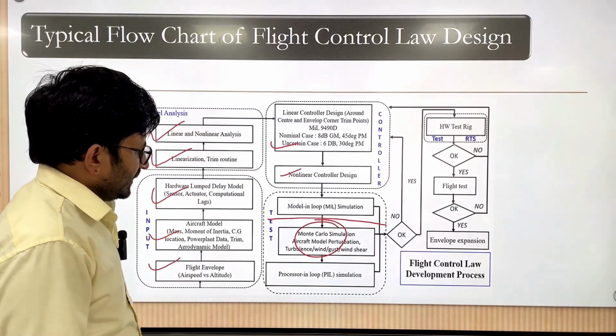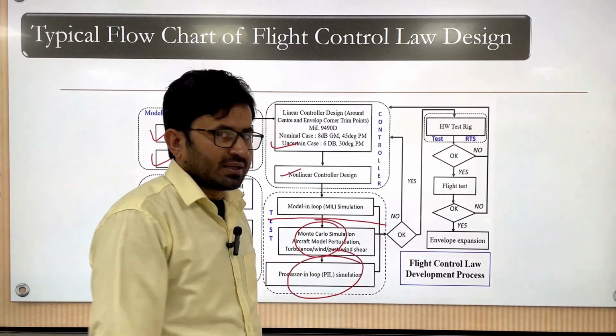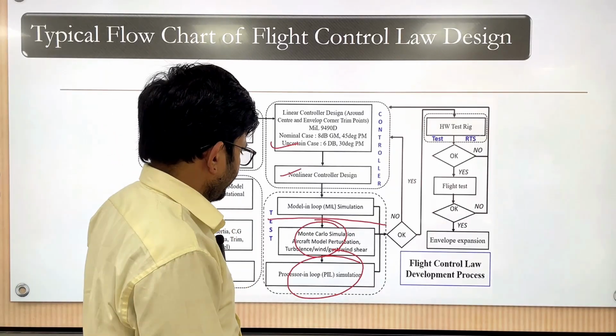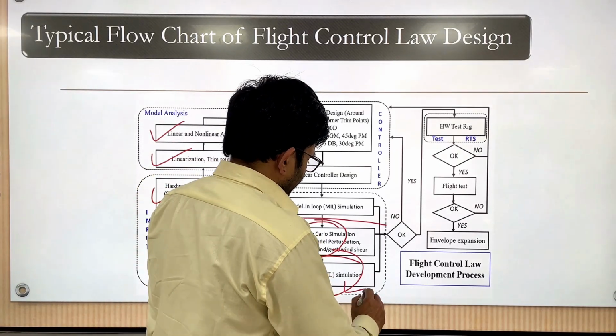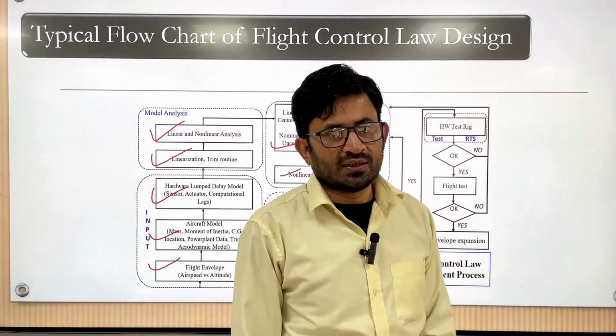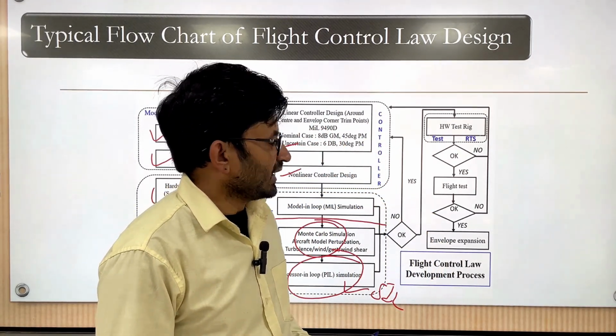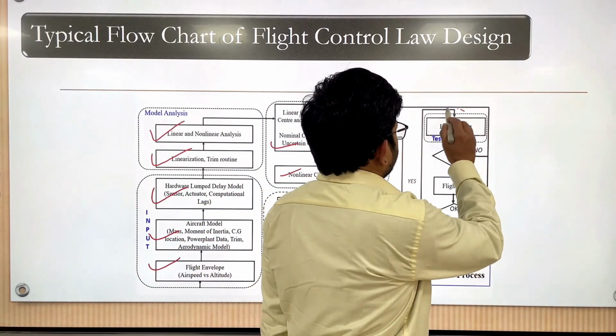Then we will convert everything into compiled code, a flight software package, and then the controller becomes the hardware, and you can actually perform the hardware testing.